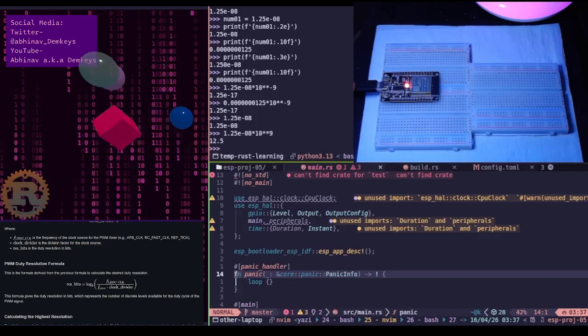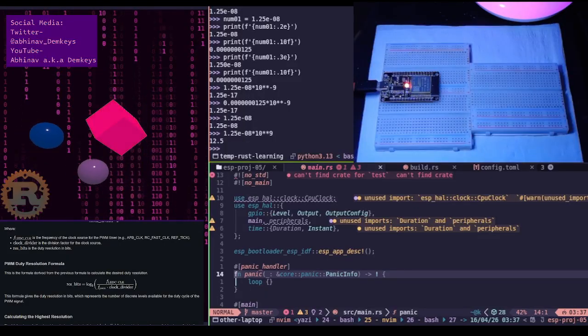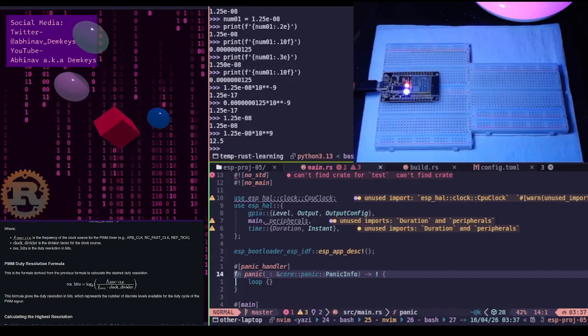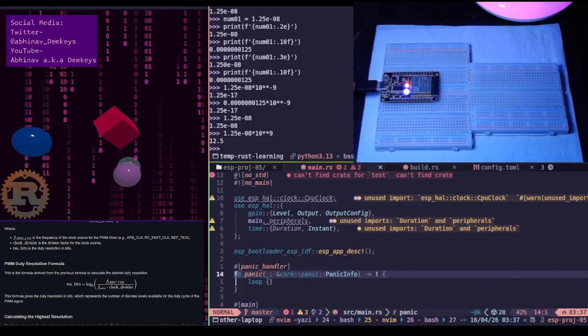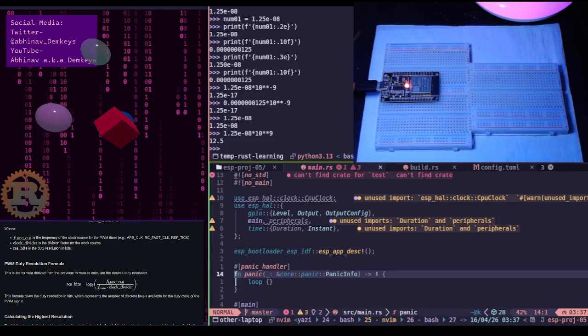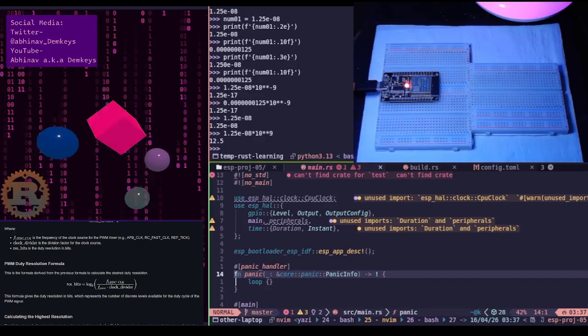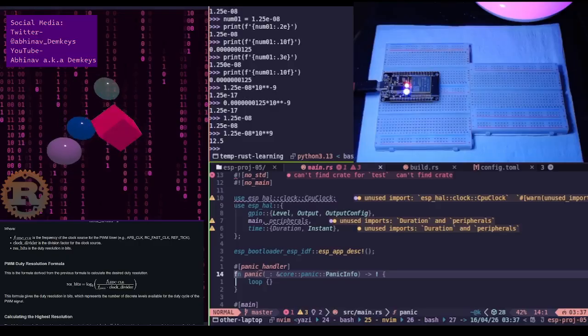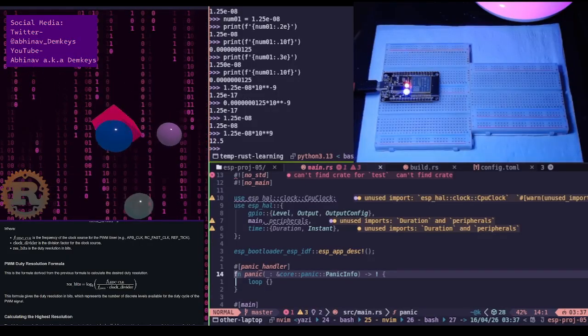The dev board takes 5 volts, and the ESP32 itself takes 3.3 volts. But if I'm powering the dev board and not directly the ESP32, I would be giving it 5 volts. It still takes significantly less current overall than the atomizer module.